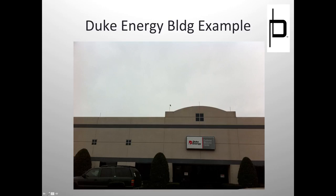The reason these are closer together is because if you take this one away, the bottom of the sphere would cut into that top part of the building. Then that top part would be subject to lightning strikes. They want the lightning to go here because this is connected to some sort of grounding system or down conductor that is then grounded. It's much safer for the strike to go there as opposed to creating a fire or who knows where it's going to go if it was to strike here. So that's why they added that extra one right there, because of that arch.